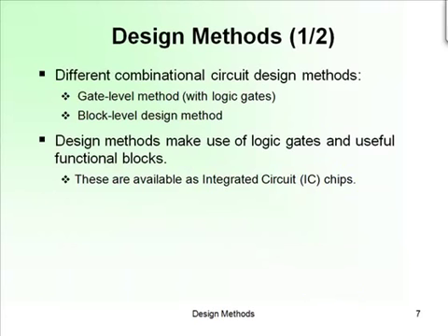So there are different methods. We can have the gate level method with logic gates and the block level design method. Essentially, I would compare this to intro C, as having code that you keep rewriting all the time, versus writing a function that you keep calling. With block level design, we can create collections of logic circuits that perform a specialized function in a macro or a module and design circuits that way, so we can have some modularity.